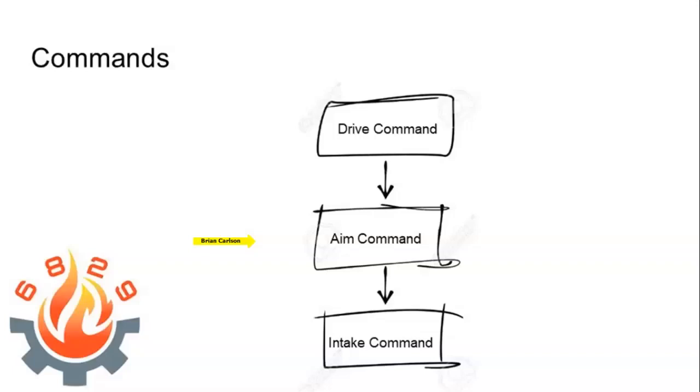The driver is trying to drive and turn. Unfortunately, because you stopped in this one command, it can't get around to the drive command to realize the driver is saying turn. So you have to be very careful that you do not take longer than 20 milliseconds. And it's really easy to make sure that doesn't happen. There's one way that, if you're not careful, you could cause this long delay.